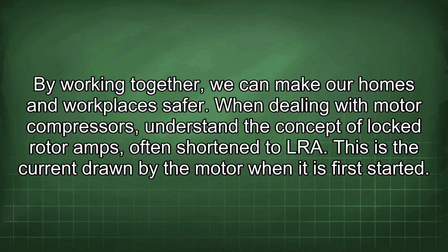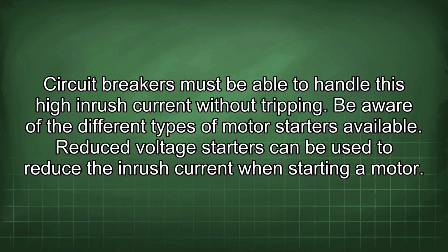When dealing with motor compressors, understand the concept of locked rotor amps, often shortened to LRA. This is the current drawn by the motor when it is first started. Circuit breakers must be able to handle this high inrush current without tripping.